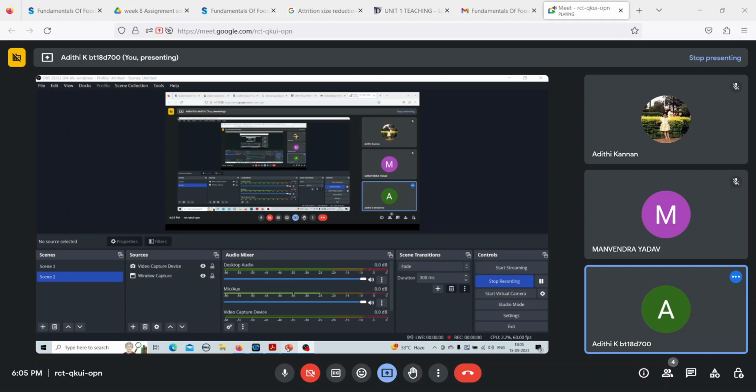Given in the question is the diameter of the roller, so R1 is given here. R1 is 0.5 meters. Diameter is given, I've calculated the radius, 0.5 meters. We know that they are 12 millimeters apart. That is, 2b is equal to 12 millimeters. So b is equal to 0.006 meters. And the angle of nip, which is 2 alpha, is 30 degrees. So alpha is equal to 15 degrees.